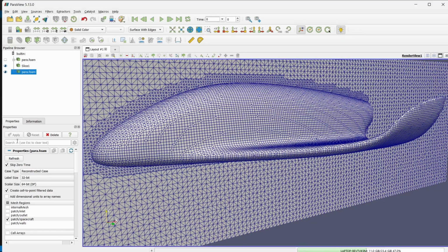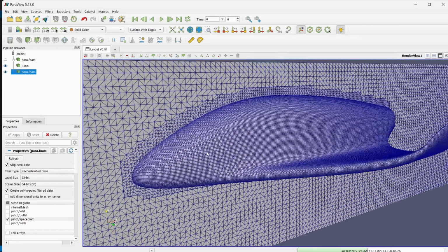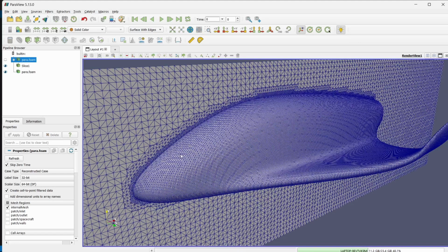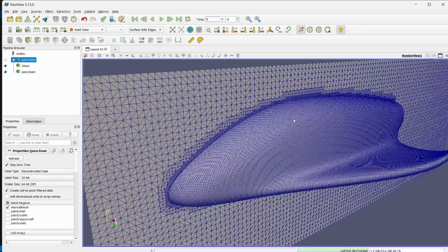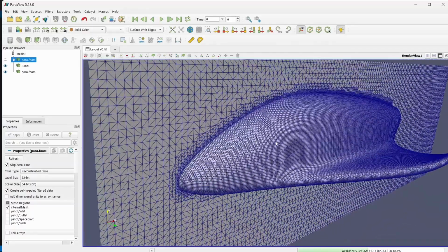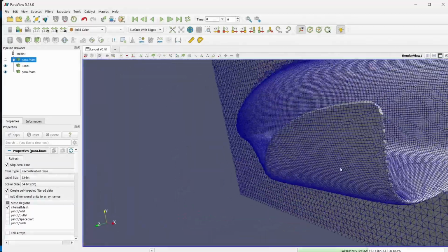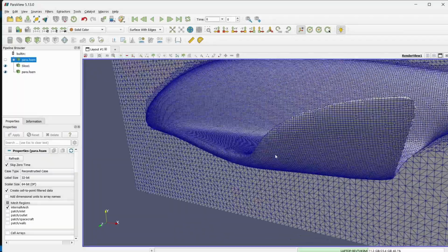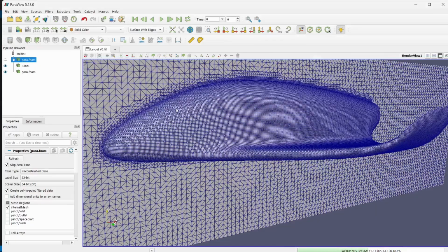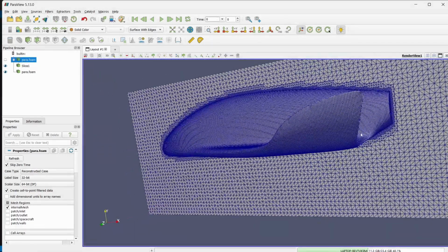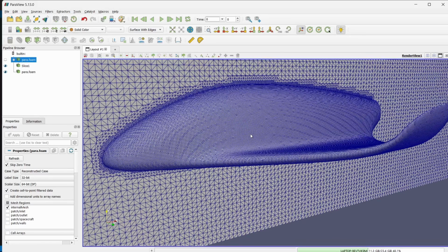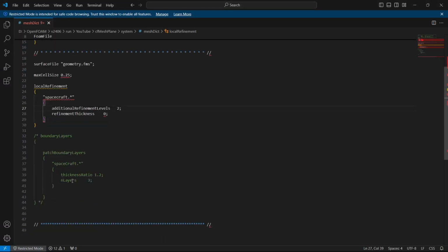Now mesh is done. I will refresh it. You can see this is much refined. Refresh this. You can see the refinement is not very far from the refinement zones. This is much cleaner, and you have also captured the features properly. That is very nice. In fact, you can refine much finer, or you can add local refinements. Everything can be done. But this is fine for me for this tutorial, because we also have to add our